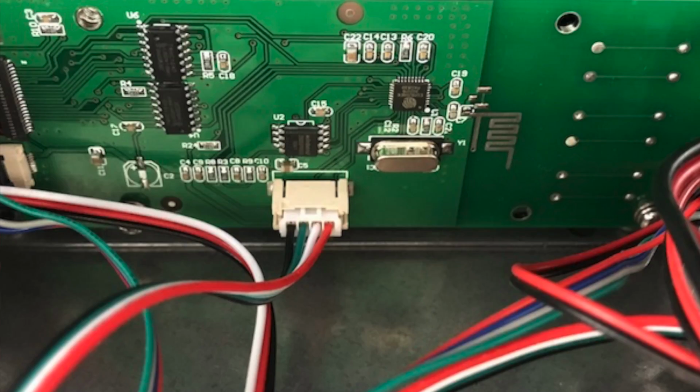They just base it off of Grbl and then built their own firmware on top of that, and have a separate chip for the UI that has its own firmware and that type of thing. That goes for a couple other similar boards coming up from Asia as well, where they run proprietary firmwares. They are 32-bit, you just can't change them unless you manage to shoehorn Marlin on there somehow.